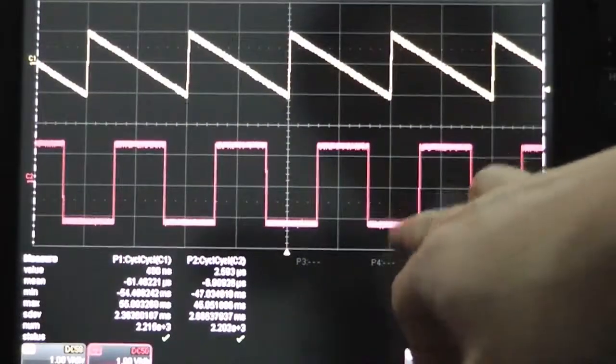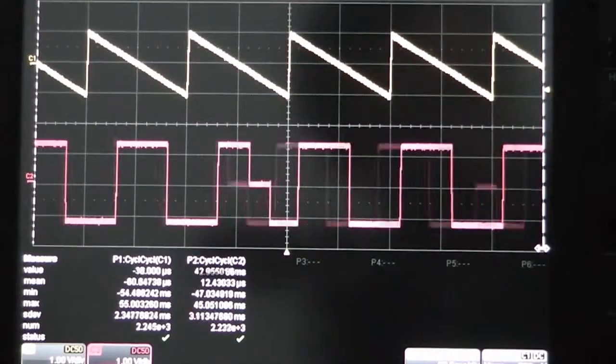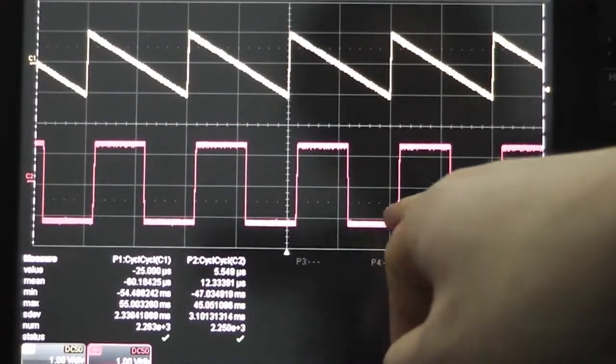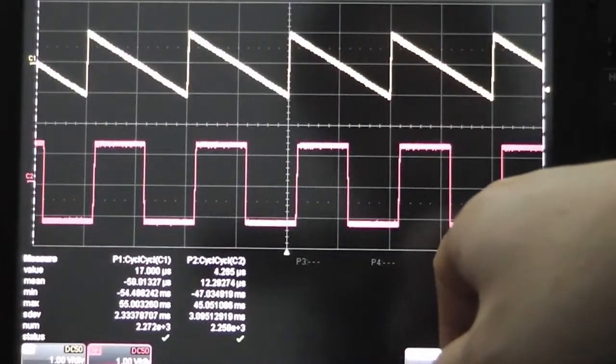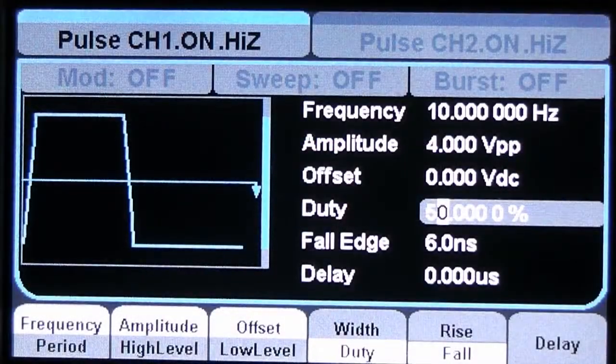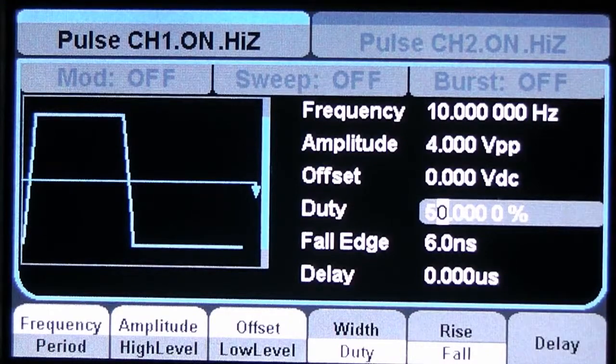Now we'll check the waveform on an oscilloscope again. The time base is set to 200 microseconds per division. Now I'll change it to 1 millisecond per division. As you can see, there's almost no change in the waveform. The duty cycle of EasyPulse can be as low as 1 part in 1 million, but the pulse width of a normal DDS generator is large and the duty cycle cannot be set nearly as low, as we see in the STG5000.